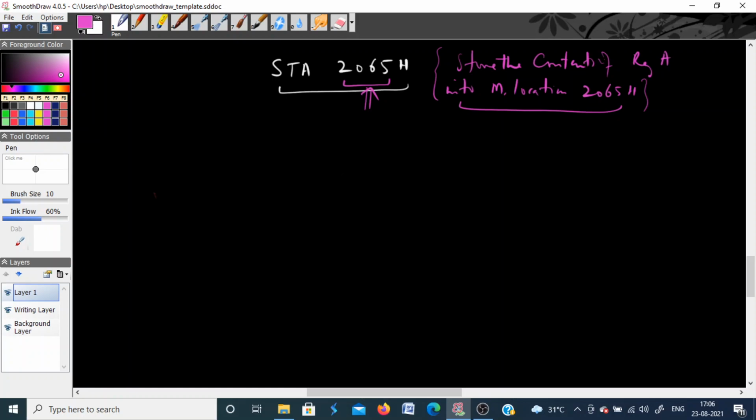You can see that it is a 3-byte instruction because the first byte will of course be the opcode. The opcode for this is 32H, and the second 2 bytes carry the address. In the last case it was MVI A, 32, so the first byte was opcode and the second byte was data.